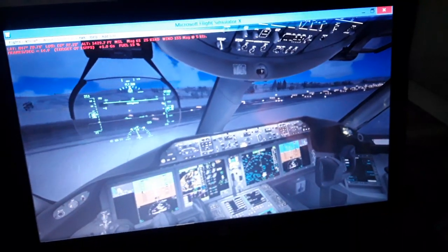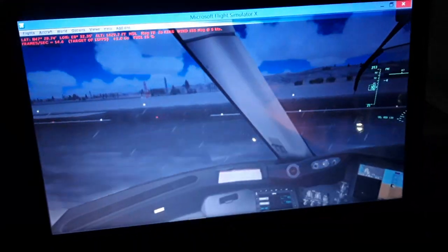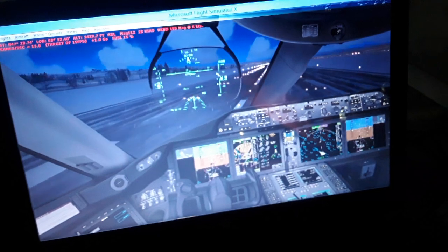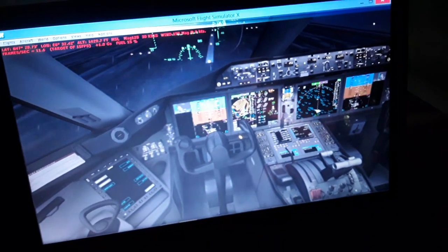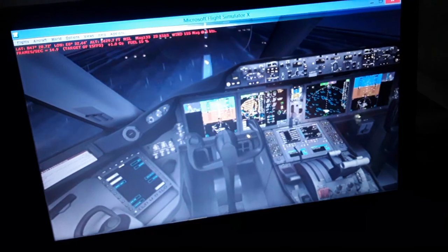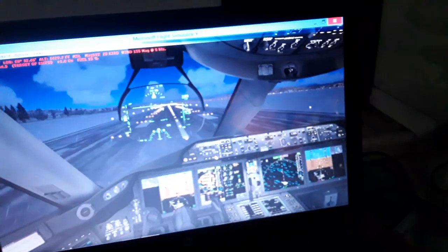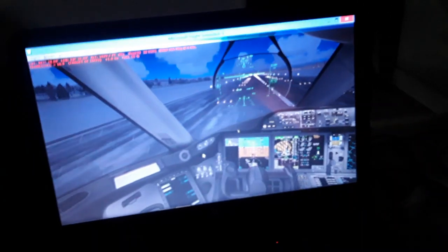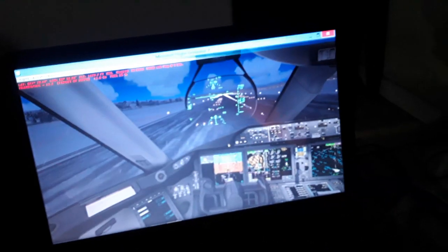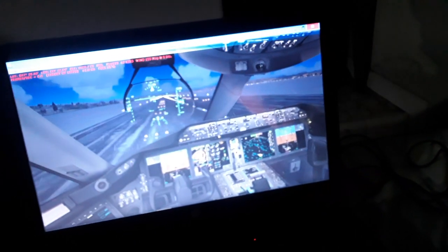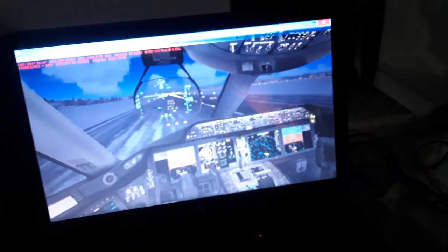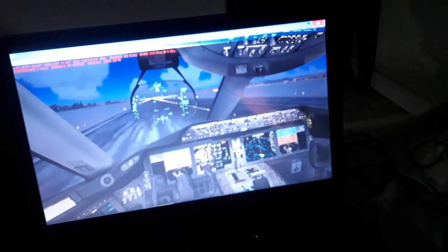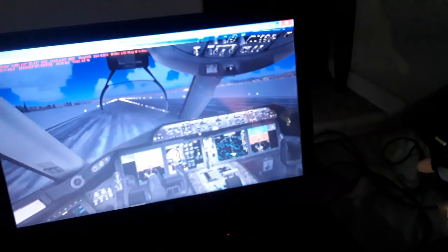So we taxi to the runway heading. Over here, as you see, align with the runway. So we use takeoff power over here and go. So we hold down the yoke a little bit as we accelerate until 100 knots, a little bit right rudder right now, left rudder.